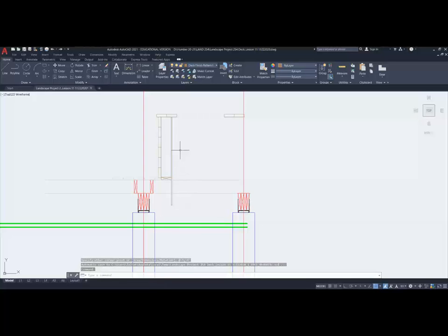And the plywood is going to provide some support for the soil that's going to be leaning into this thing. But you'll notice where I have grade, there's a bit of an opening between that. This plywood, even though I buy pressure treated plywood, will eventually rot out if I don't protect it. And this is where we use pond liner to line the inside of this, and we wrap it around, and then we'll seal it with a tape and a sealer. It's EPDM is the name of the product from Aquascape that you could use.